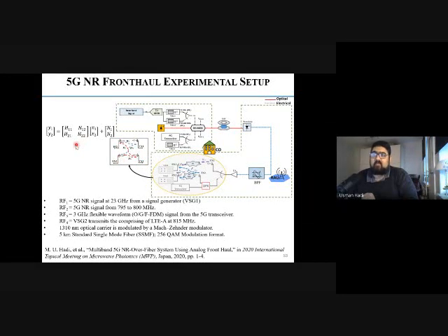So what we will have is the famous Y equals HX plus N equation, where Y is the received signal, the H are the channel matrices, X1, X2 are the transmitted signals, and N is the noise, AWGN, let's suppose, that we model.